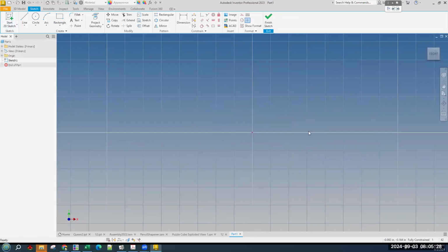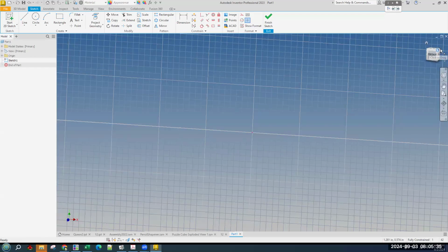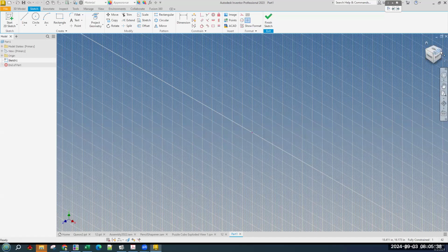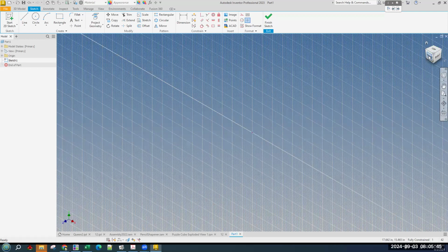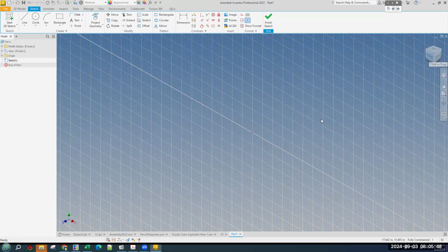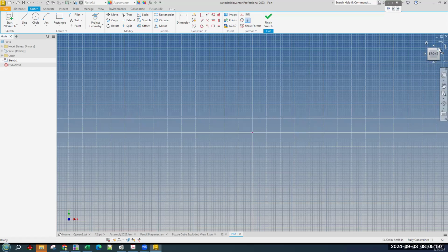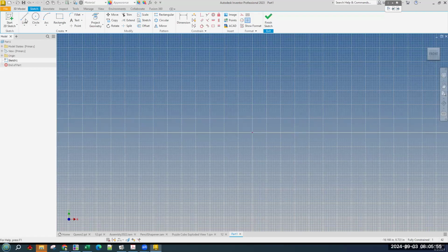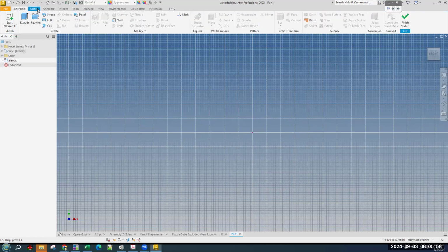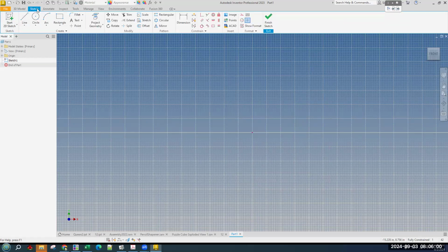Okay, so if you turn on grid lines, when you go to start a sketch anywhere, it will give you the grid lines. That is one of the reasons we turned grid lines on, is so you know you're sketching as opposed to a part mode. And this sketch plane that I've made is in the middle of the universe here on the X and Y plane, and we are going to sketch on it. And our sketch tools have popped up when we made a sketch. If you switch back and forth, it doesn't always pop over to sketch, but usually does.